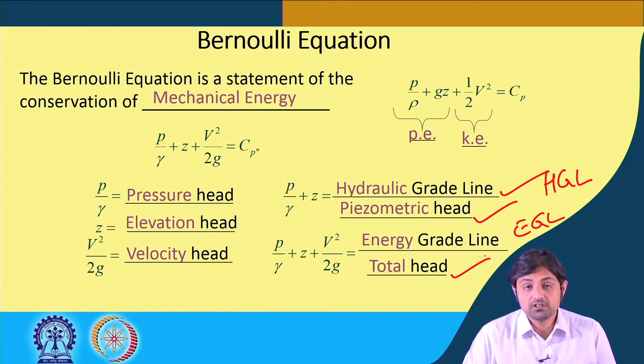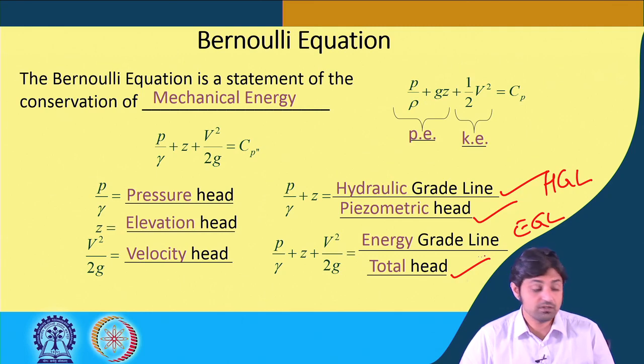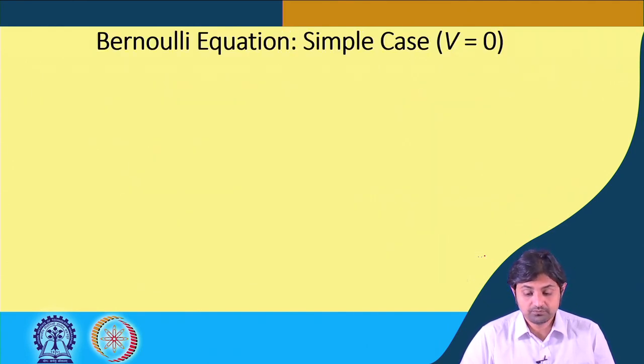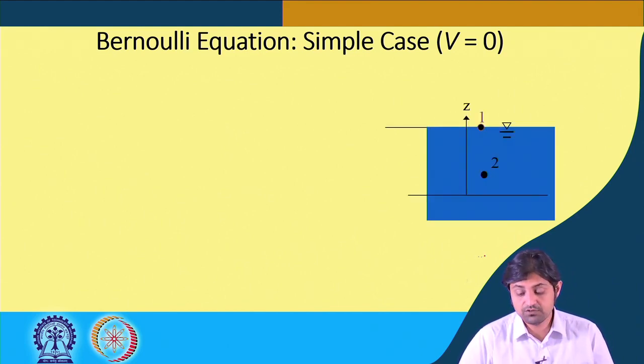This is something that you can be asked by anyone, whether you are giving a GATE exam or an interview, sitting for a company which works in hydraulics. So you must remember what the hydraulic grade line is, what the energy grade line is, what piezometric head is, what total head is. Okay. So now proceeding forward, first a very simple case where V is equal to 0.